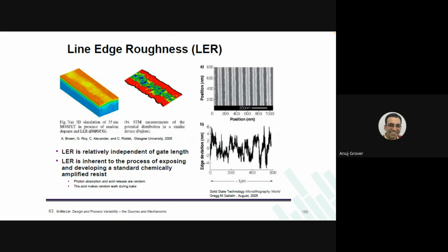Poly, the name is polycrystalline. So line edge roughness is always going to be there. We are not talking about the substrate at all. We are talking about depositing a layer of poly and then etching it out. You cannot deposit one single crystal of poly. Poly means polycrystalline. So line edge roughness, I'm not able to relate where this question is coming from.